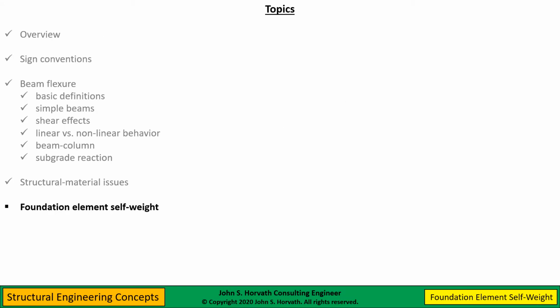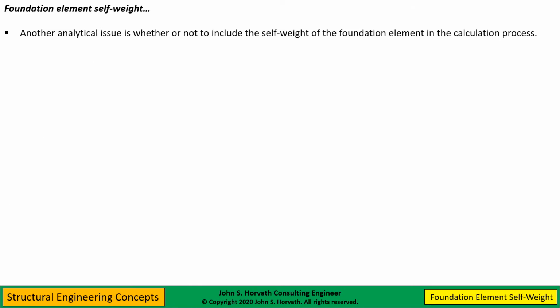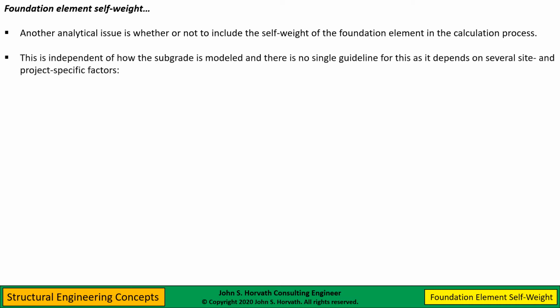I next want to talk about the foundation element's self-weight. Another thing that you see talked about in textbooks and elsewhere is, for example, if I'm analyzing a mat foundation, do I include the self-weight of that mat foundation? And the answer is there is no single answer. There is no single guideline. It really depends on site and project specific factors.